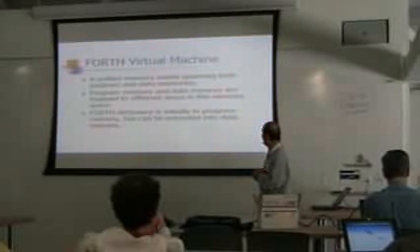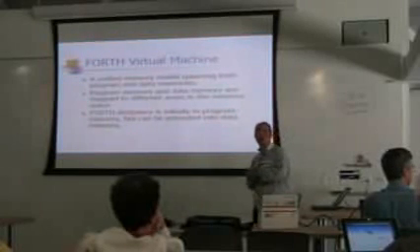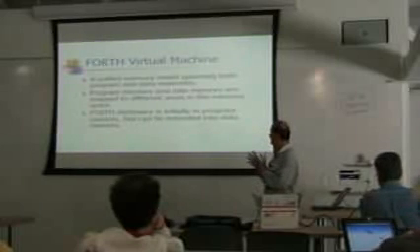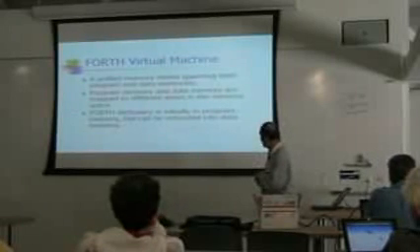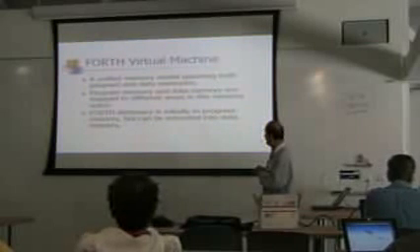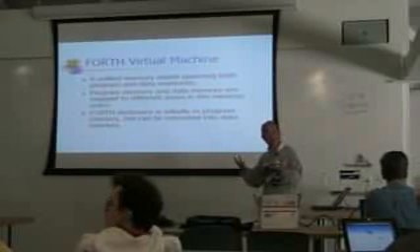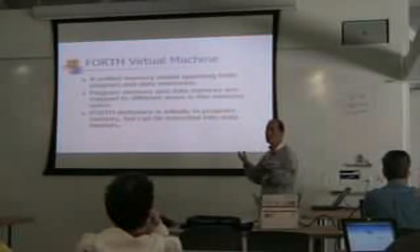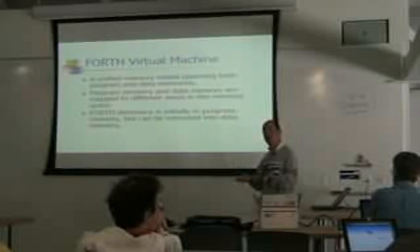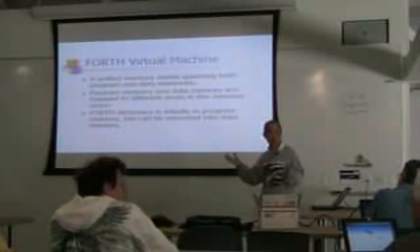With this unified memory model, with a single set of instructions which can access both RAM and flash memory, you can build an eForth system which is extendable. Originally, when you boot up, all the instructions are in the dictionary, which is in flash, as a C data structure.